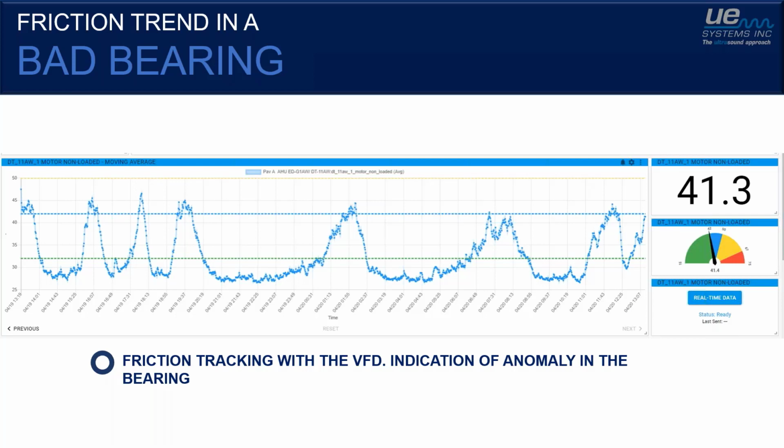That's because this is an unhealthy bearing. What we notice in an unhealthy bearing, either under lubricated or with defects within that bearing, is that you start to get heavy oscillations like this. And you start to track it. If you were to overlay the RPM or load on this same trend, you would find it matches exactly.